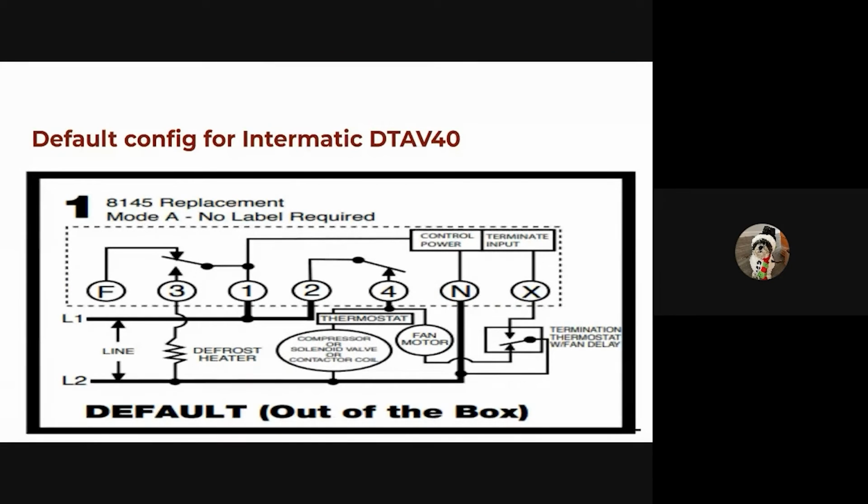So we're not providing power to fans. Well, it depends what application, whether it's frozen or medium temp. Oh, we're talking about frozen here because we have a frozen defrost cycle here. You're right. Your fans will shut off when it goes into defrost. It's typically that solenoid circuit is tied to the fan circuit, correct? Okay, yeah. I don't know why I was complicating that in my head.